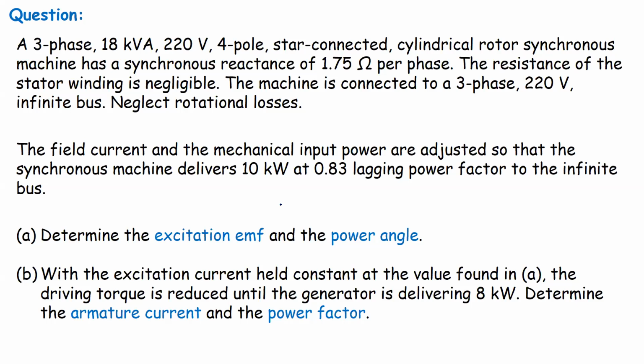The first step in solving such problems is to represent the given system in a pictorial form, especially using a per phase equivalent circuit or a single line diagram, whichever is more convenient and appropriate. In this problem, I am going to represent the given system using a per phase equivalent circuit.